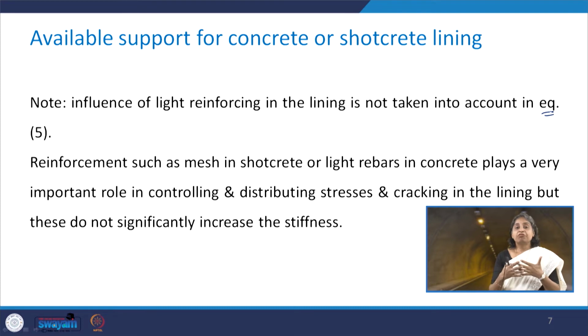So the function of such reinforcement, which are mesh in the shotcrete or maybe light reinforcement bars in concrete, is that they play an important role in controlling and distributing the stresses and reducing the cracking in the lining.